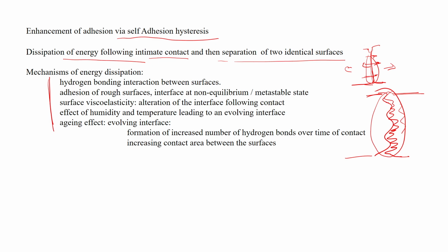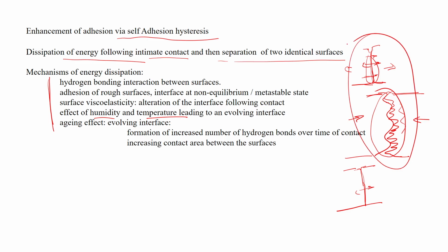So, if you give more and more time, okay, this surface will come more and more in contact, or if you apply more pressure, they will be more and more in contact. So, this situation is very different from a completely smooth adhesive, in which case there is no such metastable state or non-equilibrium state situation. The surface comes in equilibrium and the work of adhesion we find out from the surface energy and like that. Then of course, there may be other surface viscoelasticity, the effect of humidity, temperature, okay, all these things affect this basic phenomena.